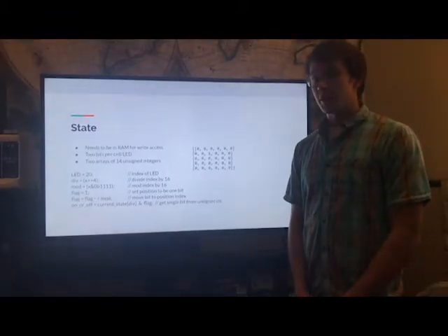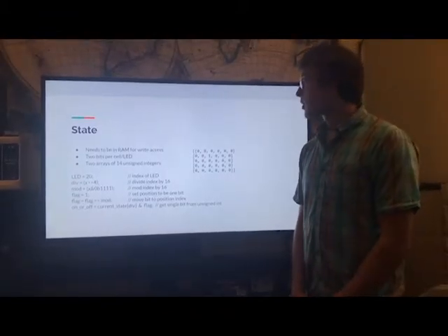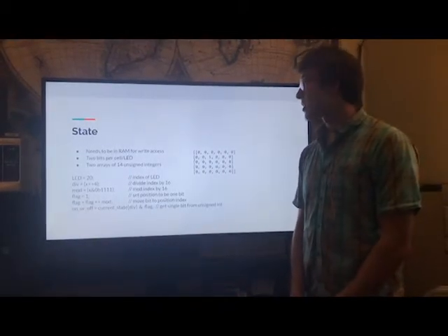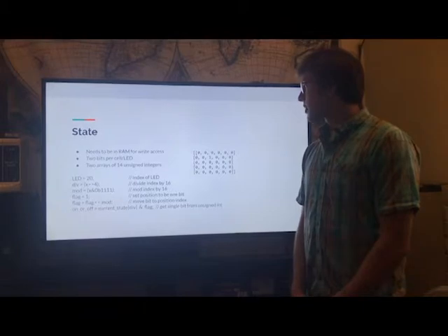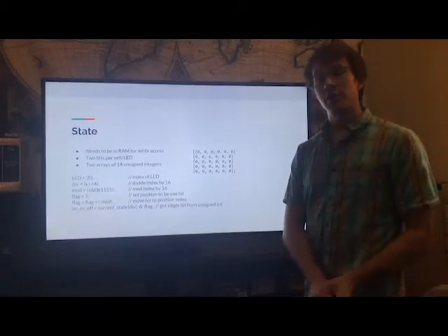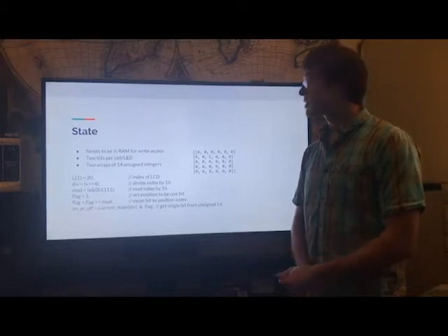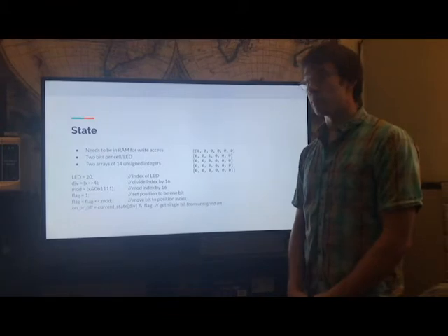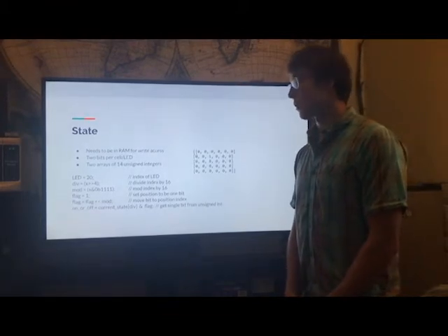It was more challenging to come up with a solution in how to keep track of the current state and next state of the LED chain. The issue here was that we needed a single bit for the current state and a single bit for the next state, but C does not provide any good way of keeping track of individual bits in a bit field, so we had to come up with our own.